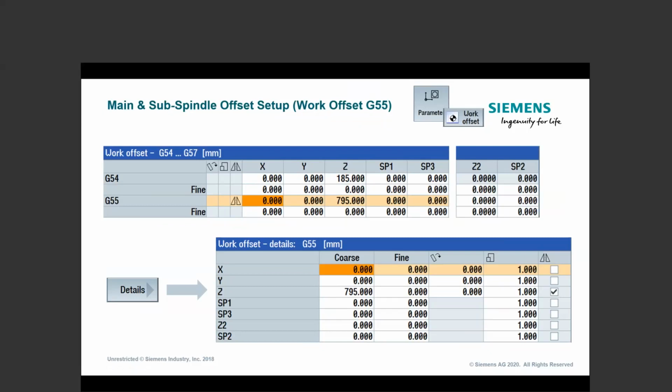So if I'm on the main spindle and I give it a Z negative, it's going to go towards the main spindle, so the machine's going to move to the left. If I'm on the counter spindle and I give it a Z negative, the machine's going to actually move towards the right. What's nice from a programming standpoint is, one, if I have common tool paths that I want to implement on both my main and my sub, they'll automatically transfer without any reprogramming.